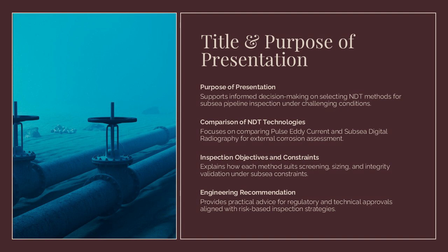The focus of this presentation is on comparing Pulse Eddy Current, PEC, and Subsea Digital Radiography Testing, SDRT, two advanced inspection technologies that are frequently considered for external subsea corrosion assessment. The objective is not to declare a universal best method, but to explain how each technology performs under real subsea constraints, what defect mechanisms they are most suitable for, and how they align with inspection objectives such as screening, sizing,